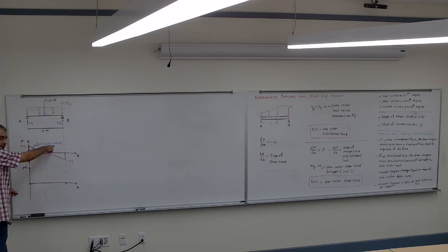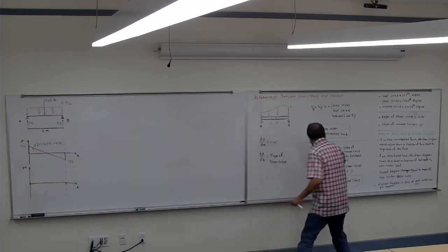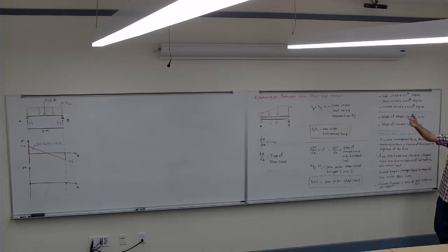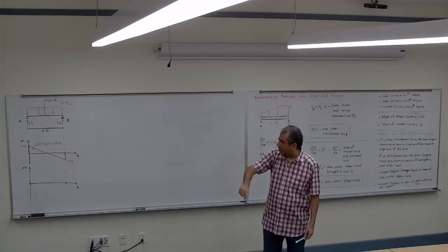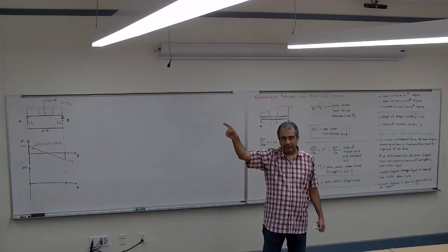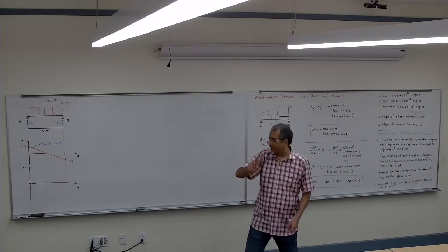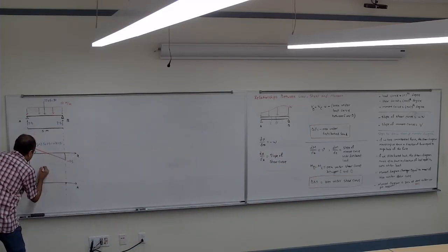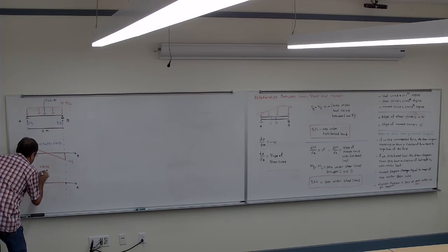So that's what our moment is, positive. Yeah. So the moment goes from 0, look at here, delta M is the area under the shear curve. So the area under the shear curve, the change is positive 31.25. So it goes from 0 to 31.25, with the degree of 2. So I know that when I get there, it's going to be 31.25 and second degree.